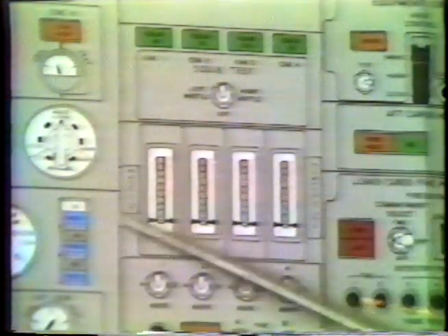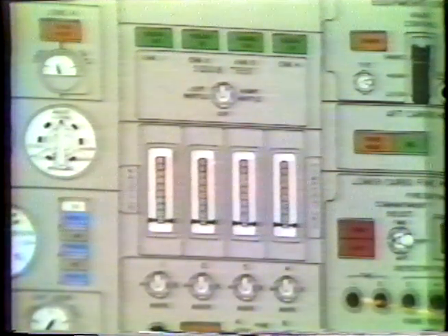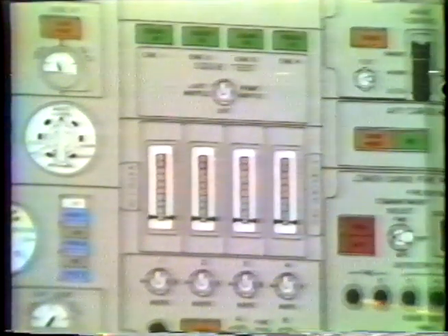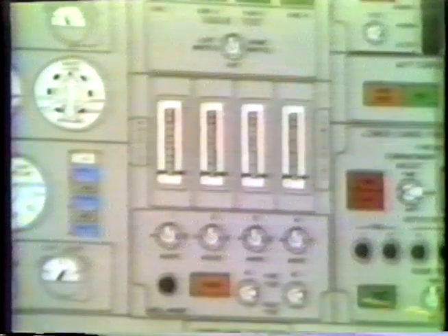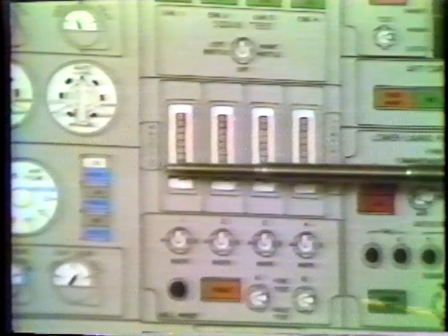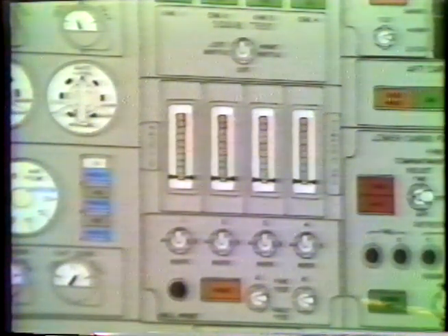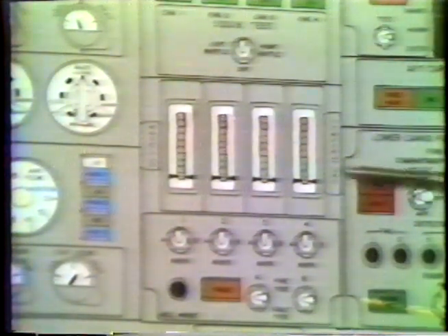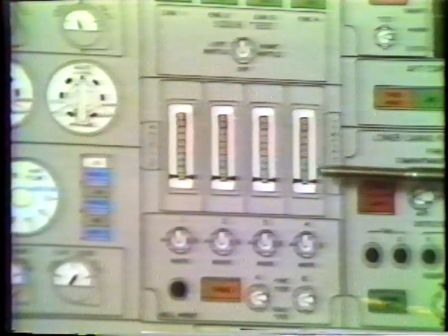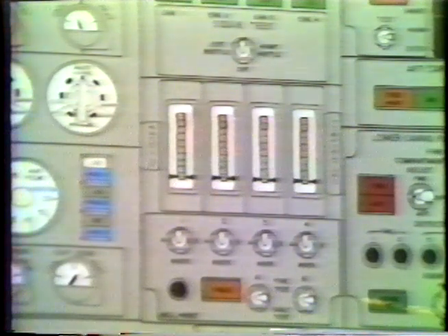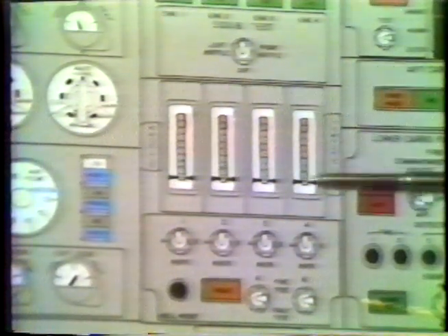Next I want to talk about these pointers here. The pointers represent roughly the temperature in the area of the fire detection loop. Normally the pointers lay at the bottom or near the bottom of the scale for all engine operation. If that area starts getting warmer than normal, then the pointers will move up, and generally they move up together as the two loops are side by side, and would indicate other than abnormal temperature there. Usually in the green band,